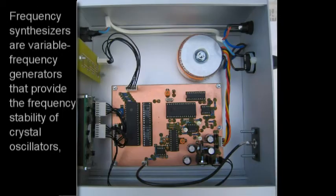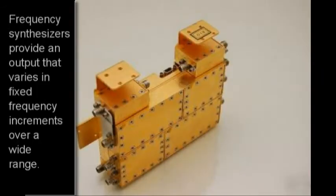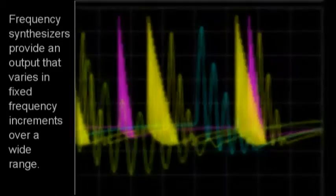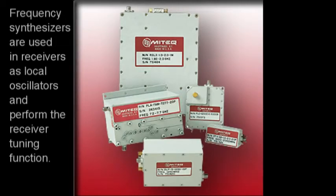Frequency synthesizers are variable frequency generators that provide the frequency stability of crystal oscillators, but the convenience of incremental tuning over a broad frequency range. Frequency synthesizers provide an output that varies in fixed frequency increments over a wide range. In a transmitter, a frequency synthesizer provides basic carrier generation. Frequency synthesizers are used in receivers as local oscillators and perform the receiver tuning function.